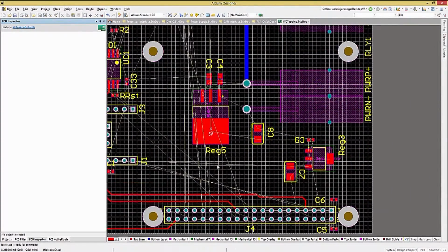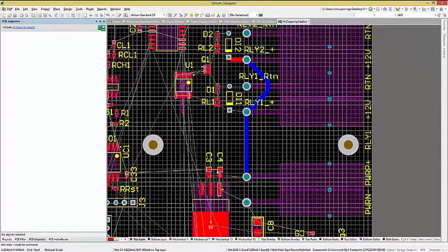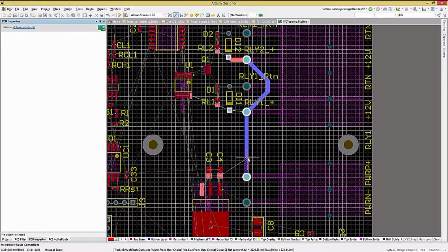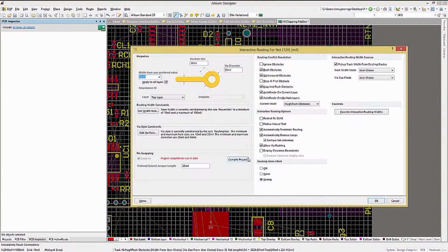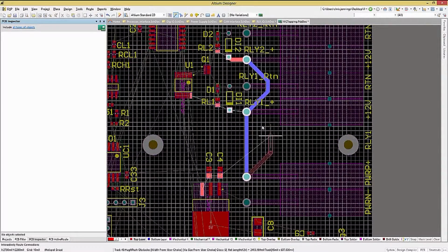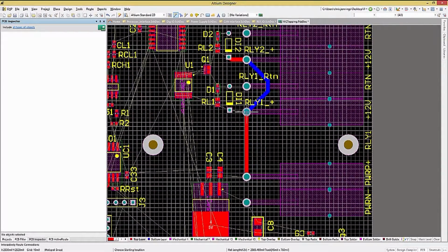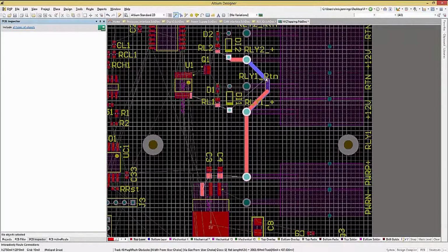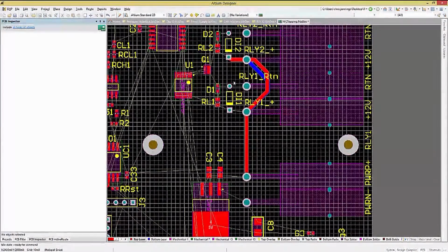Once I have finished the parallel tracks, I switch back to enabling the loop removal. Note it does not retroactively remove loops, but if you modify a net with parallel tracks in it, it will perform the auto loop removal, so be aware. Note, hitting the Tab key while routing, you can set or unset the automatic loop removal setting. This is a more convenient way to change loop removal when in the midst of routing rather than navigating to the preferences window.